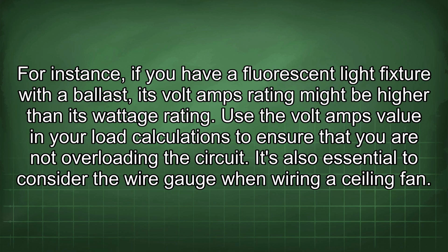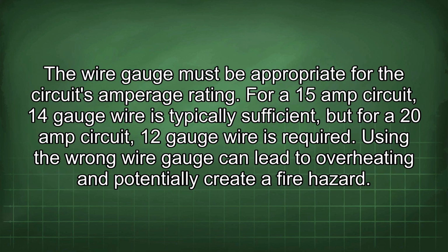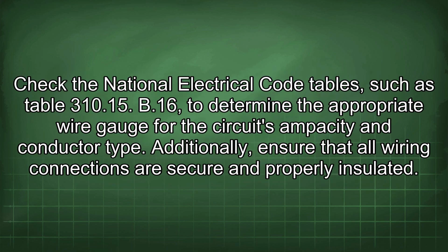It's also essential to consider the wire gauge when wiring a ceiling fan. The wire gauge must be appropriate for the circuit's amperage rating. For a 15 amp circuit, 14 gauge wire is typically sufficient, but for a 20 amp circuit, 12 gauge wire is required. Using the wrong wire gauge can lead to overheating and potentially create a fire hazard. Check the National Electrical Code tables, such as Table 310.15(B)(16), to determine the appropriate wire gauge for the circuit's